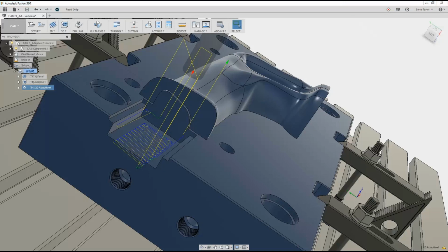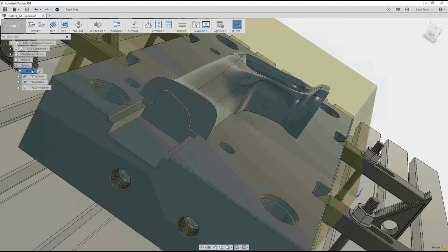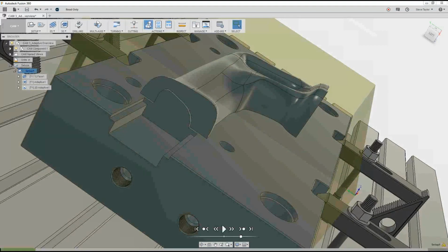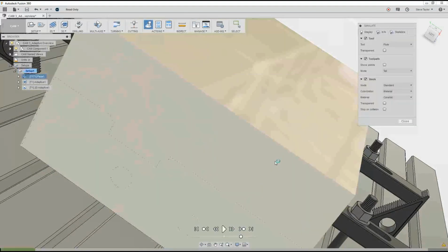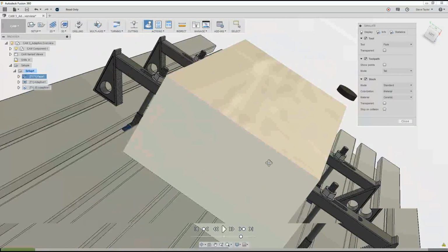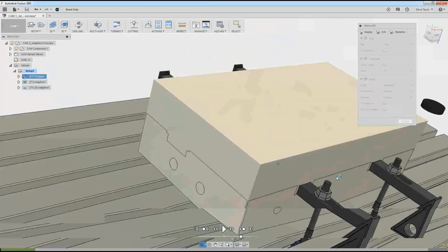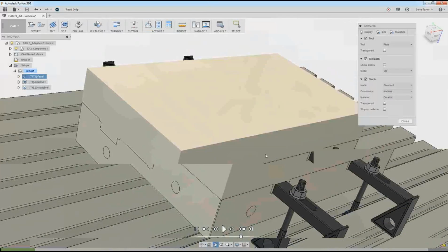One thing I really like to show people, and as soon as this pocket's done, which is great, is I'm going to choose Simulate in our Action tab. So what I'm going to do, I'm going to first of all select the full setup, and then in the top up here, if I select Simulate, it brings up this Simulate box. Now this has carried forward my information that I'd set in initially.